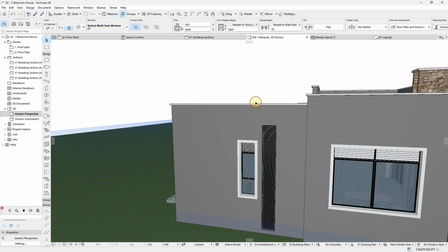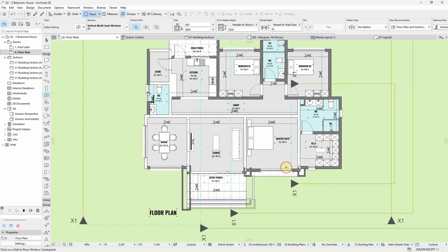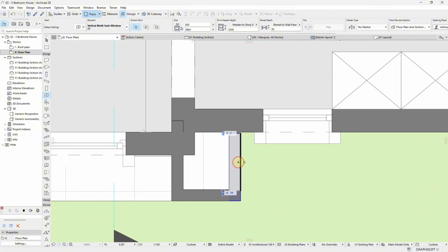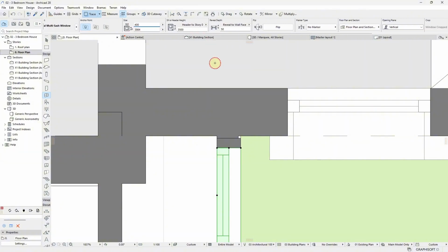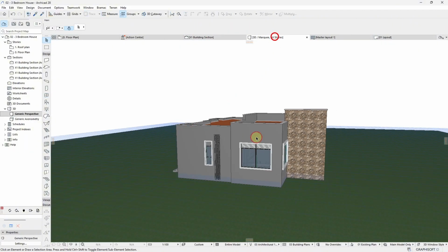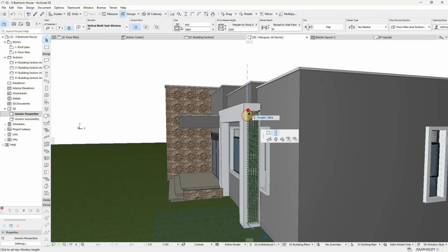At least somewhere there. Actually, it's over the roof level here. So I do the same thing. I select it from that side. I have another duct here where I'll position this. So I'm just going to make it like 400 millimeters, so it will be hidden at the back of this. That's for us to do any repairs in case of any leakages and so on. This will be used as an inspection door.